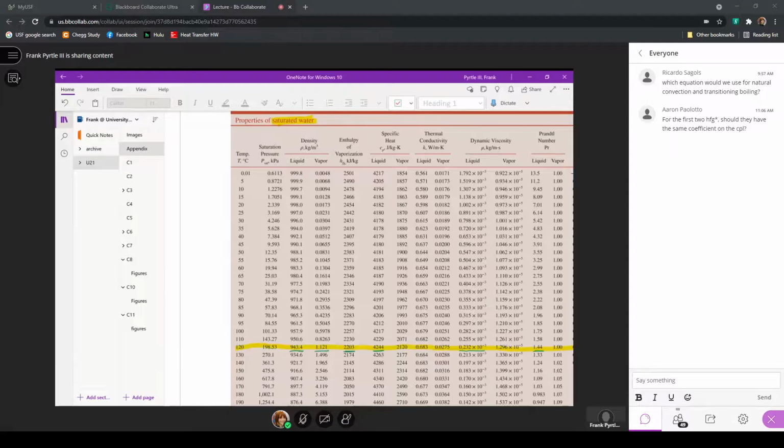In the condenser section, both for water and for R134A, or just any refrigerant, we have a changing of phase from a vapor into a liquid, where we're again able to provide relatively high heat transfer rates into and out of the fluids based on the phase change that's actually occurring in the fluid at a constant temperature, that is the saturation temperature associated with the pressure for that boiler, that condenser, or that evaporator.